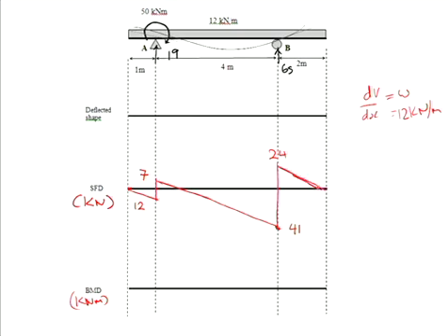So in this instance, our shear force is linear throughout because we have a UDL load on throughout. For cases where people didn't have a UDL load, your shear force can just continue horizontally across. There's your shear force diagram.